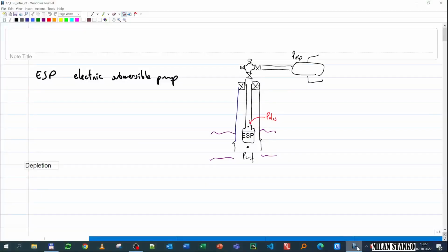Welcome. In this lecture I want to give an introduction to electrical submersible pump, also abbreviated ESP. So ESP is an artificial lift method that consists of threading a pump to the tubing and putting that pump as close as possible to the formation to increase the pressure between what's coming in and what's coming out. And I want to make it as close as possible to the formation such that it has best effect.